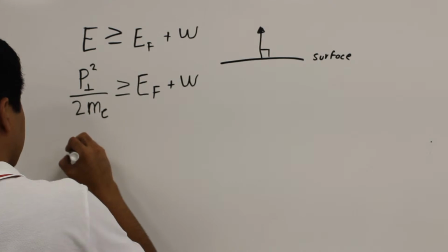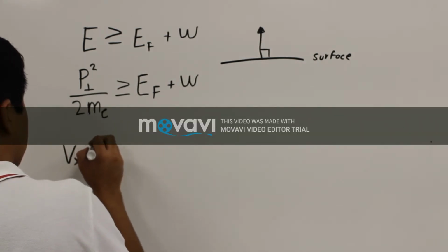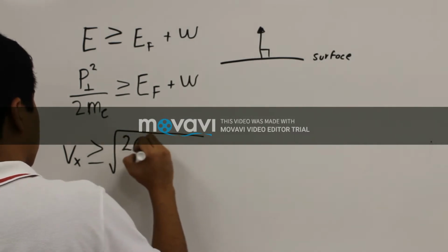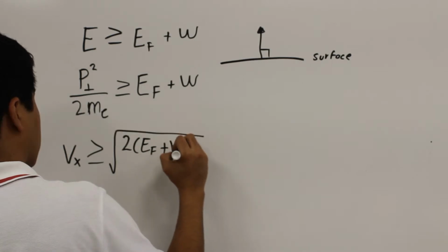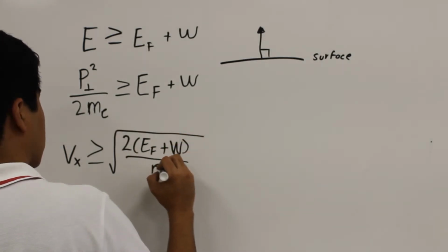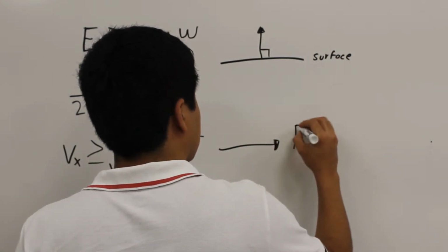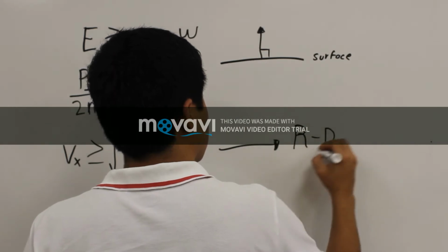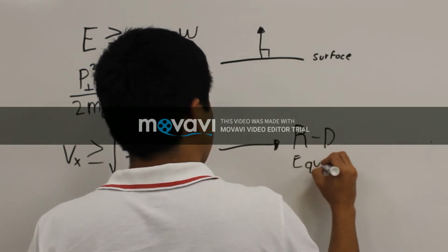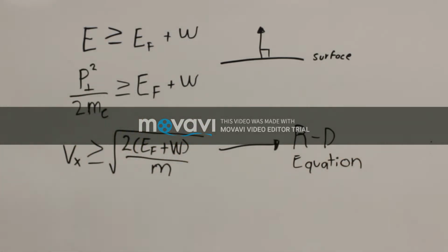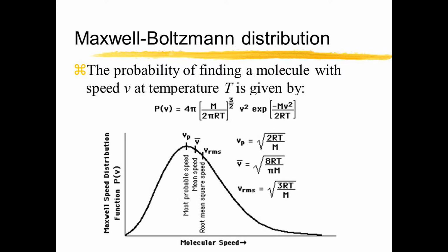Then we can rewrite in terms of the velocity in this direction. So whenever this x component of the velocity is greater than this relation, the electrons will overcome the surface forces to contribute to a saturation current density emitted by a cathode. With this knowledge, a temperature-dependent saturation current density can be calculated, as Owen Richardson, a British physicist, did in 1901. The laws governing the behavior of electron emission include Richardson's law for thermionic emission.